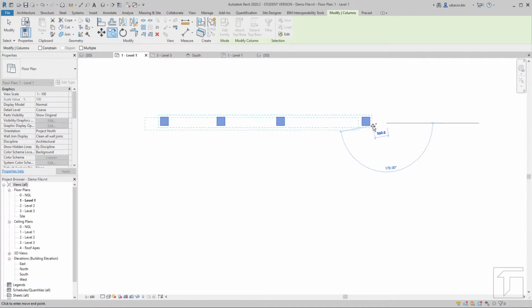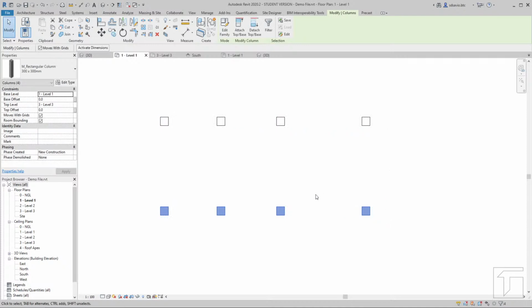So this is actually the origin spot. Also, it gives me an angle. Since I want to copy it straight down, I'll make sure that the position of my mouse is also at 90 degrees, as you can see on the guide there. So let me just place here. Again, I'll not be strict with the distance first for this roughing in of columns. So let me click to finally place the copied columns there.